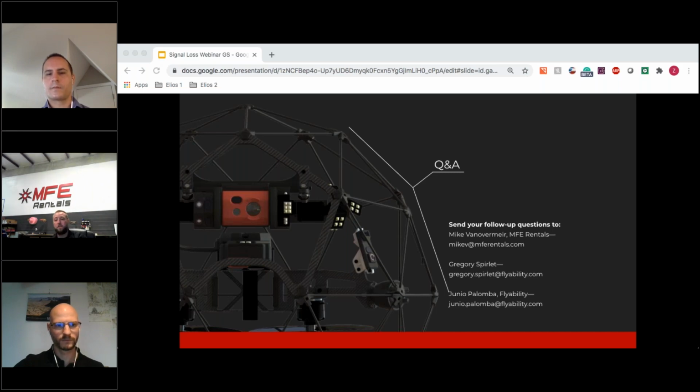And what I have witnessed is that dust does not have nearly the impact on signal strength, because it's usually surrounded by something such as metallic structure that kind of outweighs the dust that's there. Dust is going to act very much like water as far as absorbing that signal. But again, with the materials that are around it, the signal has seemed to stay fairly consistent in those types of environments. So while I think that's a great question, I just haven't run into a situation where dust has killed the signal strength relative to what else is around it. Sure, that makes sense.